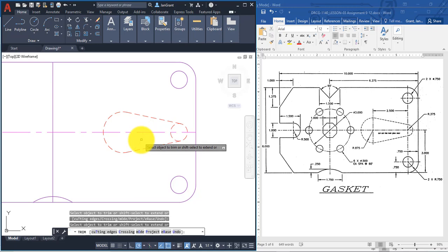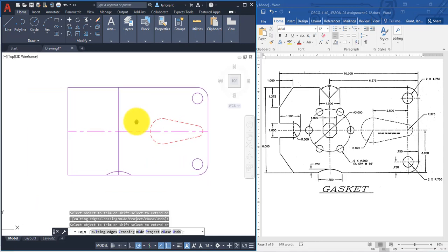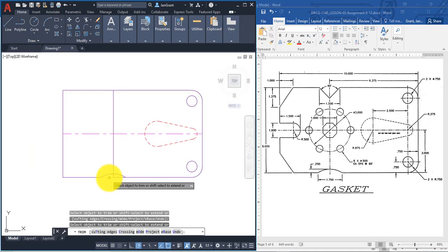If you have 2020 or anything earlier, when you start the trim command, you press enter, and then it brings you to the same idea of being able to take out those objects that you don't need back to the first cutting edge. Okay, since I'm here and trimming, I can also take out these two lines at the bottom next to a part of this arc to make it a clean cut. All right, so now let's take a look at this left edge here.